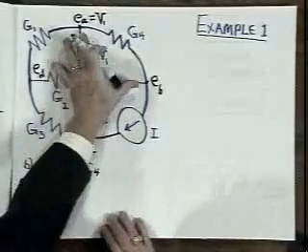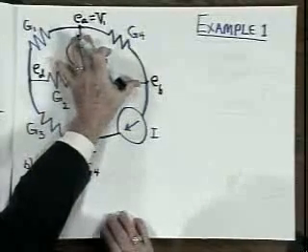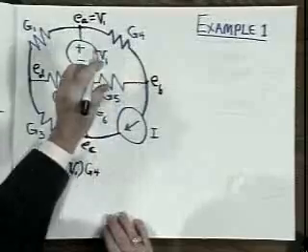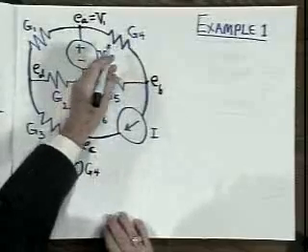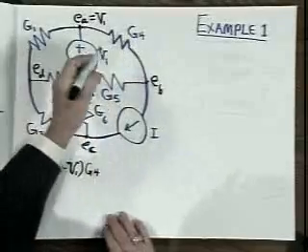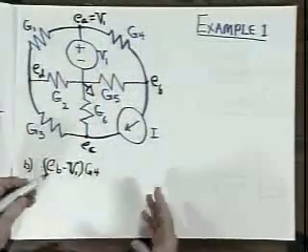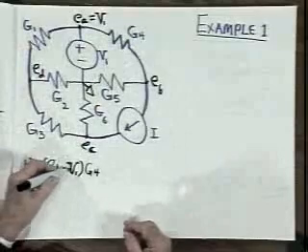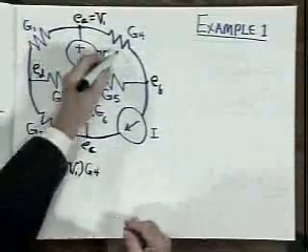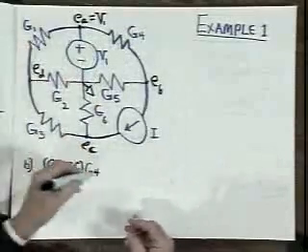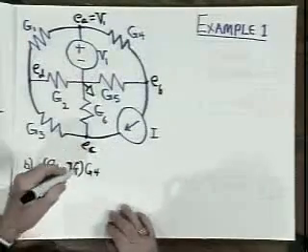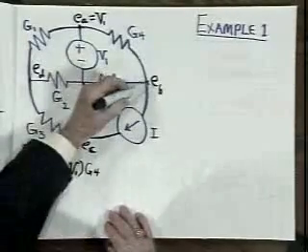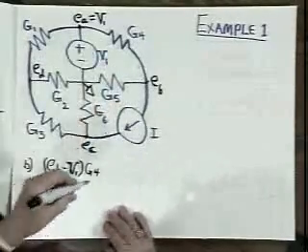The voltage difference multiplied by the conductance gives us the current in this element. That's why I chose to write conductances instead of resistances. Had I used resistances instead, I'd have to write E sub B minus V1 divided by R4. And it's just easier to have it all in the numerator. So this is the current out of node B through G4.